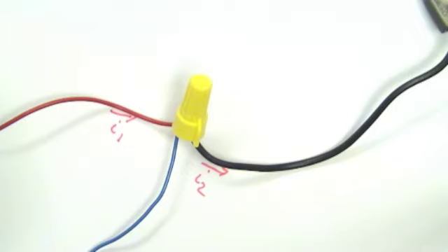Now we have a third wire, so there's going to be a third current I3. Do we want to have the arrow in I3 pointing away from the node or toward the node? It doesn't really matter, but in either case we want to have a systematic algebraic way of writing Kirchhoff's current law at that node.